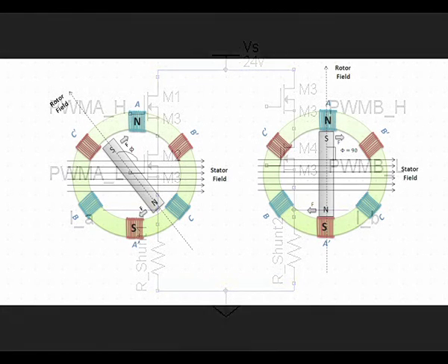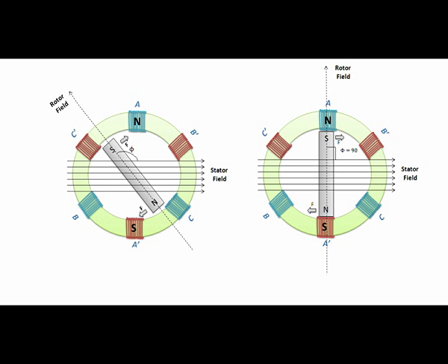The demo uses field-oriented control or vector control. I will refer to this as FOC. FOC is one of the methods used in variable frequency drives or variable speed drives to control the torque and thus finally the speed of three-phase AC electric motors by controlling the current fed to the machine.